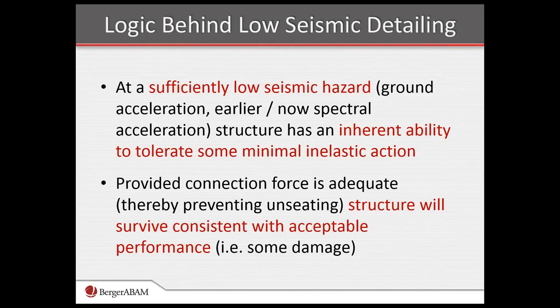And there are several strategies that can be used here. But the idea is that potentially, even in the low seismic category, the structure may see a small amount of damage, but would survive, consistent with that performance. And what we're talking about here, where we're permitting damage in, say, the design earthquake, is really the general category in terms of use for the structure, not higher operational classifications where you may want immediate use of the facility after a design earthquake.